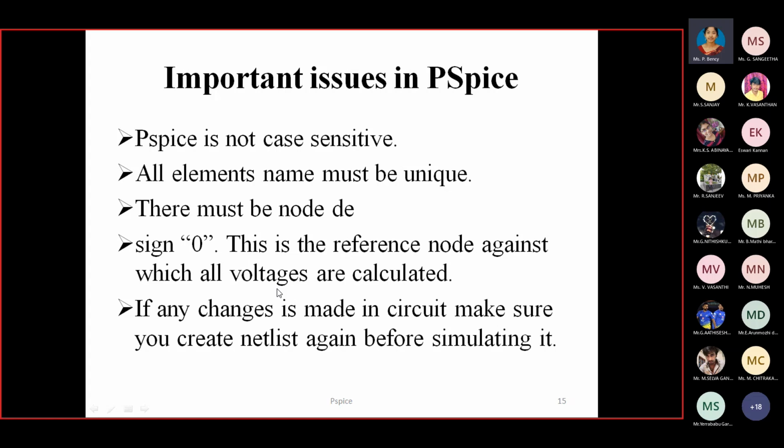In our analog circuits, we will be using a ground or earth. In our digital circuits also, we have some voltage levels. If we do not place the reference 0 in the analog or digital circuit, we cannot simulate the designed circuit.